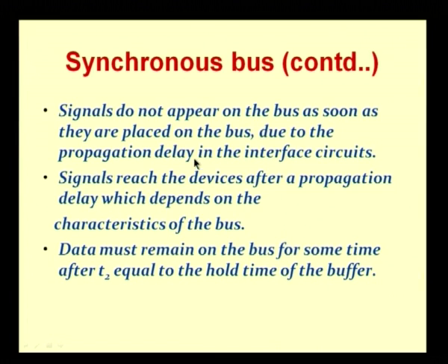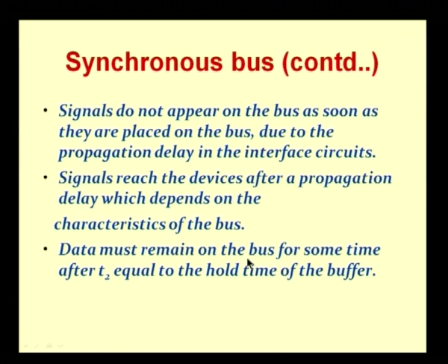Remember, there are two different propagation delays we are talking about over here. One is the delay it takes for the signal to go on the bus itself, and the second is the delay in the interface circuits of the input output device that you are talking about. So before it can be placed on the bus, again there will be some delay. Okay. So both these delays have to be taken into account. And data must, as I said, remain on the bus for some time after T2, which is equal to the hold time of the buffer.